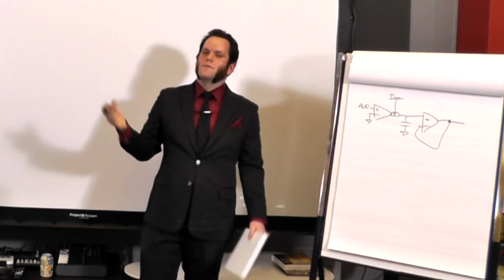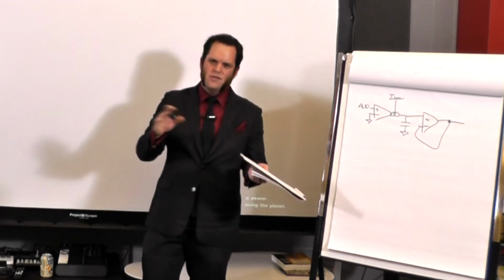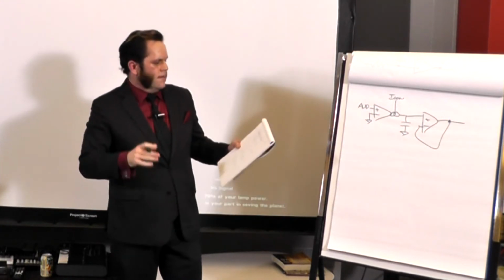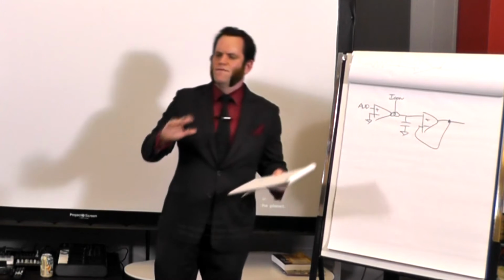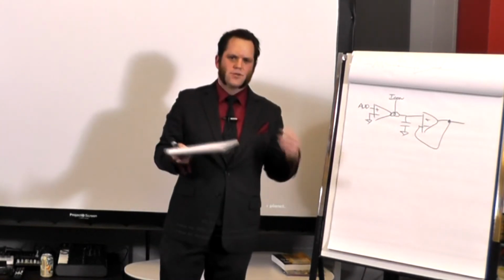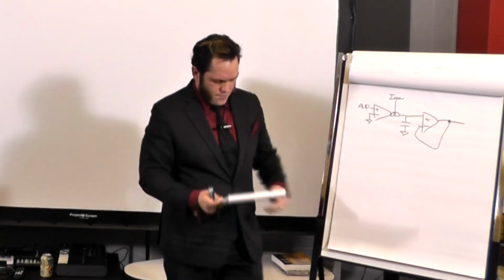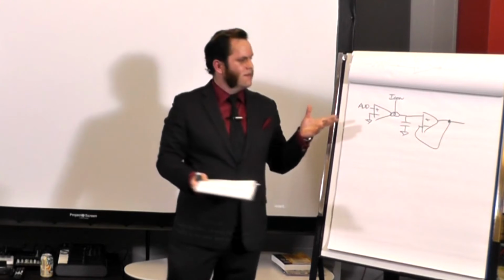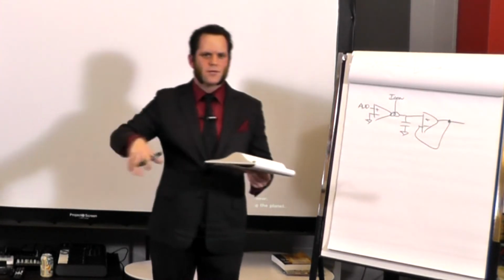So now we have a simple structure for admittedly a 1-pole VCF, and 1-pole is kind of boring, but it still does some cool musical things. And if you want to, you can stack a whole bunch of those on top of each other and get like a 4-pole VCF with some fun resonance and other crazy things, because we're trying to up the cool factor here, and 1-pole filters are kind of lame. But most analog synthesizers will just stack a whole bunch of stuff on each other and throw hardware at the problem because hardware is expensive.